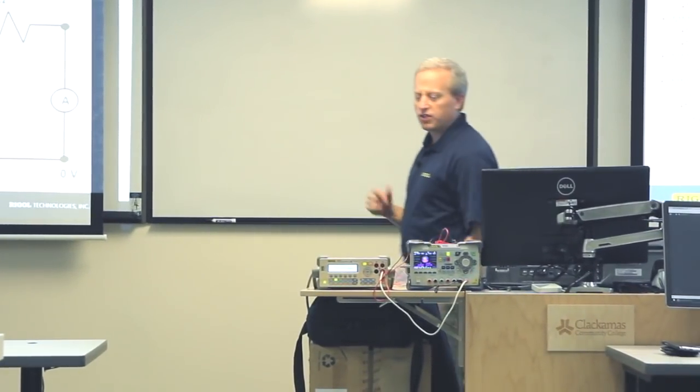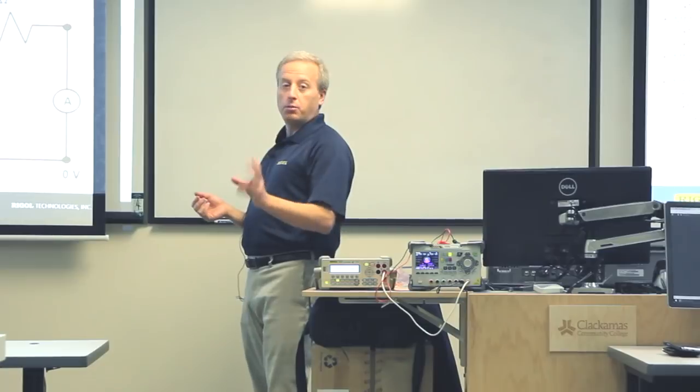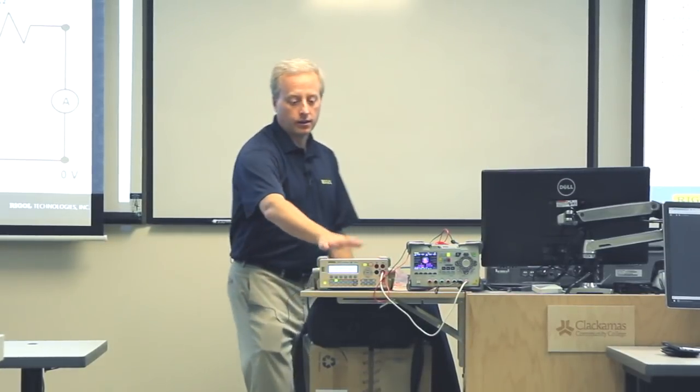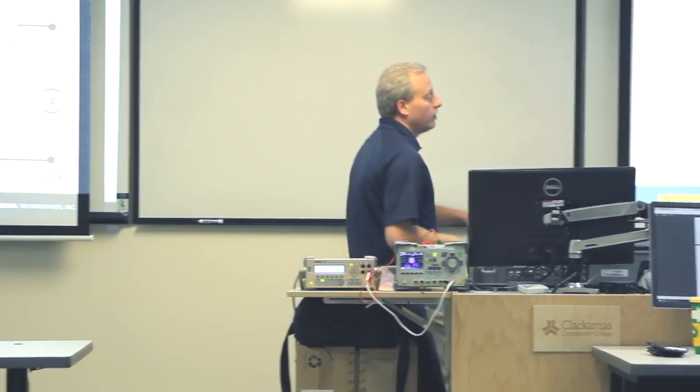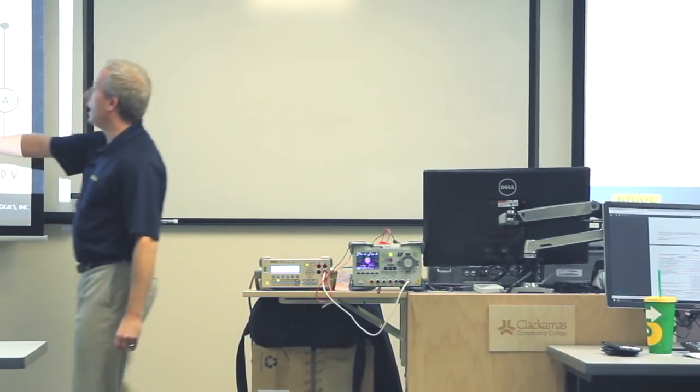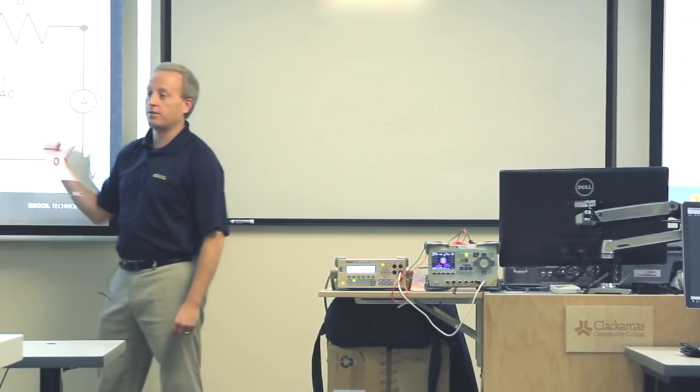So, and this is one of the differences we'll talk about between a multimeter and an oscilloscope. A multimeter, like the one on your bench here that we're using, typically has tens of gigohms of input impedance. A gigohm being 1,000 megohms or a billion ohms. So that high impedance forces all the current to flow in another direction.